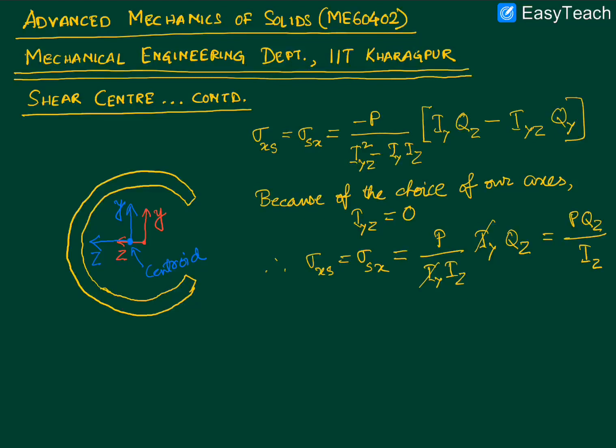Why am I making such a big deal of this very niche point? You see, ultimately we have to find out the torsional moment of the shear stresses which would be distributed over this thin member. Now, it is much easier to find out the torsional moment of the shear stresses which are distributed here about this axis which is passing through the center instead of this one.